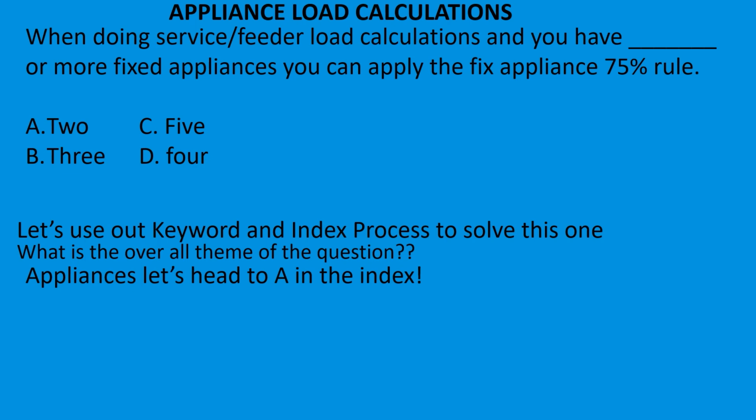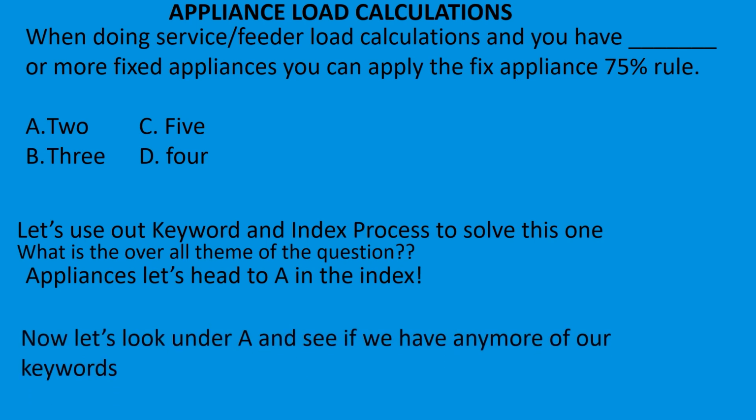We're talking about calculation, so let's see if there's anything in there about calculation. We look down. In C, nothing about calculations. Let's keep going. We get to L, and it says load calculations. So now we know we're in the right spot in our index process. There are several different code articles listed under load calculations, so let's go to the first one.